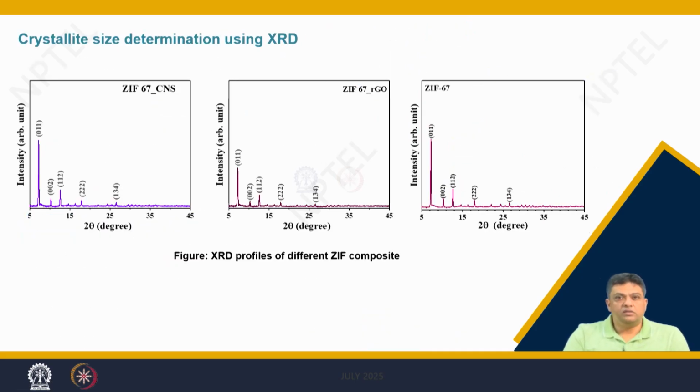So, you collect the intensity versus 2 theta curve. You take the powder, put it on the sample holder, you have an incident beam and the detector moves in the 2 theta circle. So, you have theta 2 theta movement and you get the value of 2 theta at which the peaks are appearing. Then you index them, assign the Miller planes to the peaks which are giving these